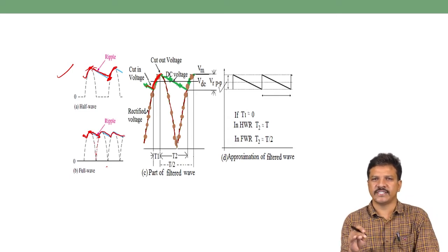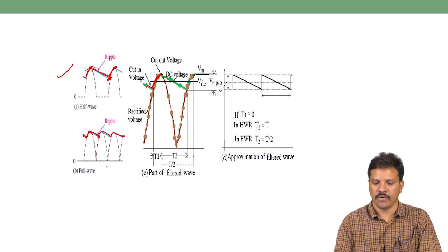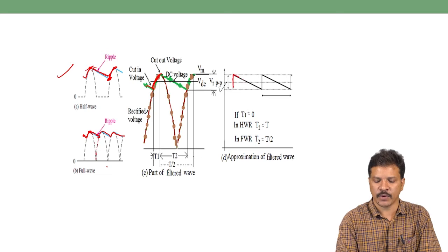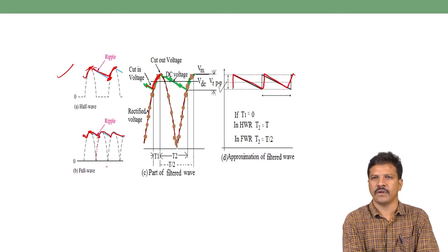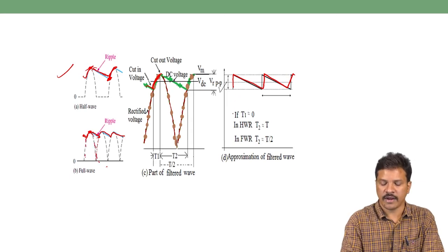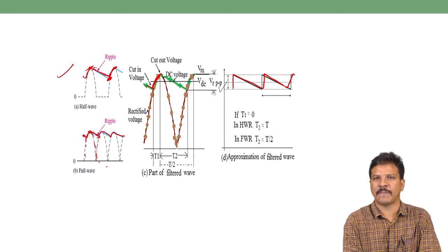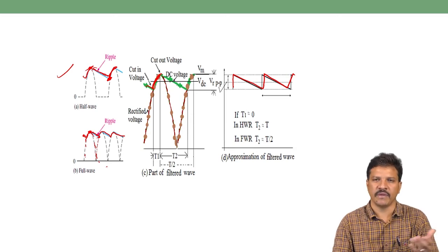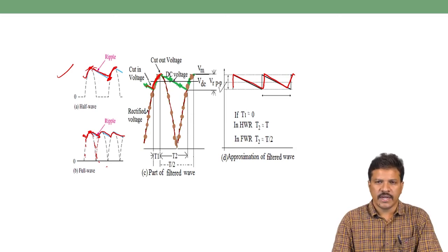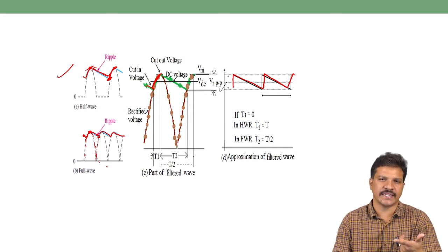This charging and discharging of the rectified or filter output waveform can be mathematically approximated to this kind of triangle waveform. When we compare it with this dotted line, the rectified output, the waveform of the capacitor filter has less AC component and fewer ripples compared with the rectified output. It is important to note that the diode has a low resistance, ideally zero forward bias resistance.